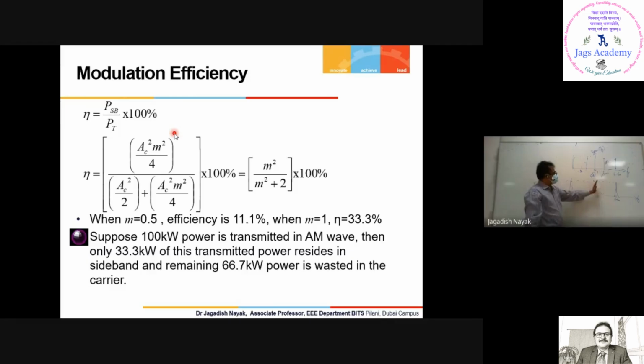Okay. Now see, when you multiply these two, when you multiply spectrum of DSB-SC and this H of f, can you tell me what will happen? This is multiplied, all these are 0, right? This is multiplied by 0, everything will become 0, but this is multiplied by 1. So only this frequency will be coming at the output of the filter. Have you understood this? So how do you generate now single sideband suppressed carrier wave?